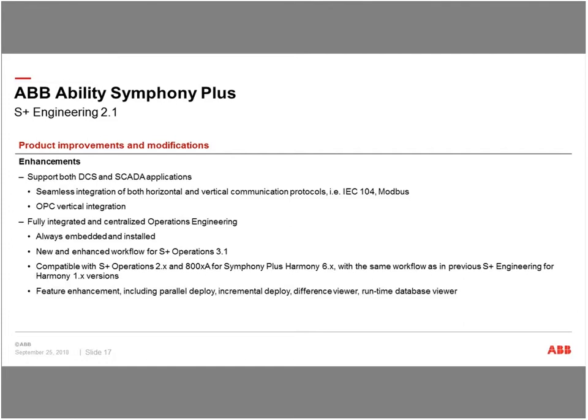Like you are running your DCS, but you probably want to integrate another third-party PLC running some auxiliary system, and you want to have a universal operation for that. And then you can use this feature. We call it vertical integration. That's basically just letting your operation HMI directly talk to the third-party device by this standard protocol.